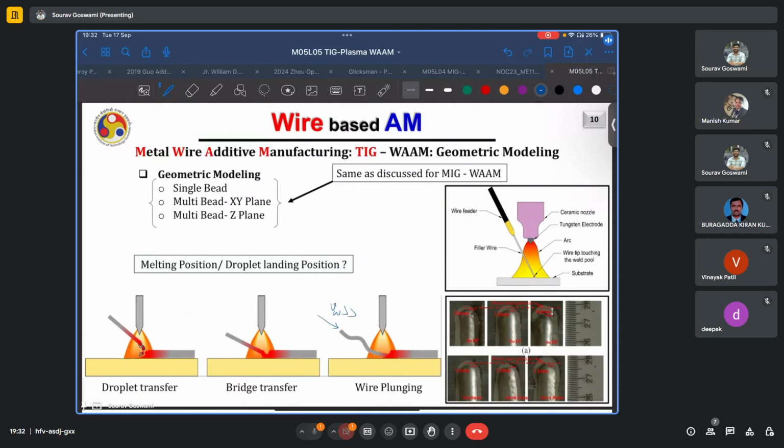Or will it be this equilibrium type of configuration where the wire is being fed at an optimum speed? It gets molten, but it only gets molten very near to this melt pool. Say if this is the melt pool. And thus we have this liquid bridge, which connects the incoming electrode wire with the existing melt pool. And the deposition is occurring almost in a quasi steady state fashion.